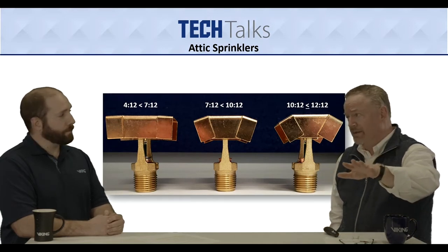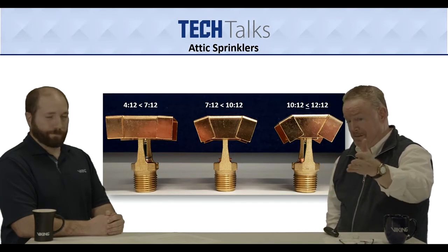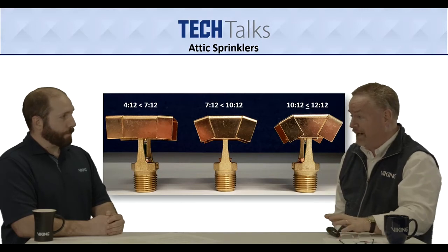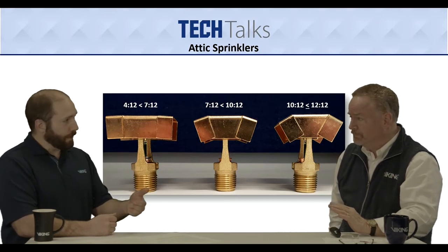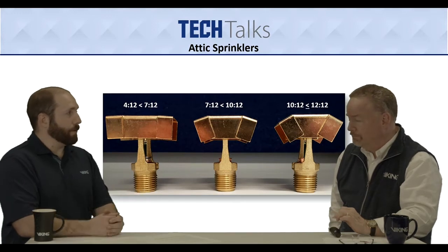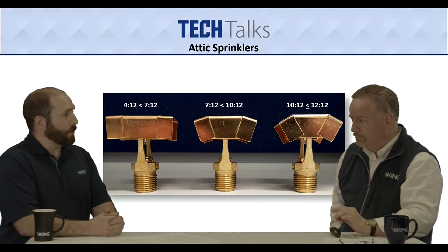So first thing, when you're ordering or looking at this building, it's really important to know your roof slope, because we've got 3 different ones all in this back-to-back range. Yep, there's a couple different K factors, 5.6K and 8K. But we also have them with a unique shape to their deflector to match the slope of the roof. So you can see the really flat one. We can go 4 and 12, and then it gets more angled all the way up to a 12 and 12 pitch roof slope.